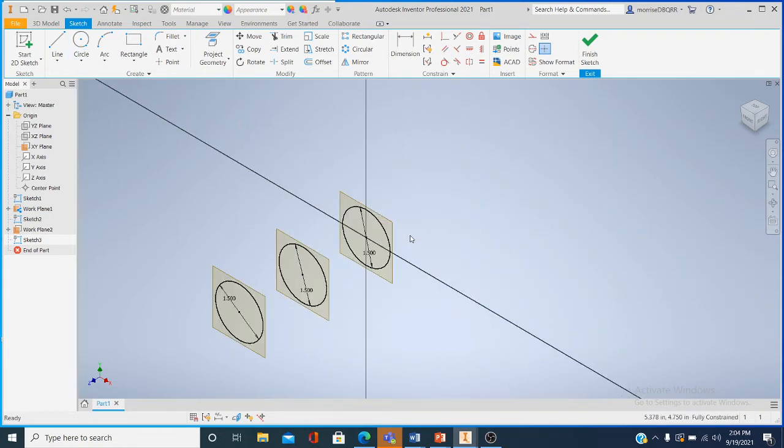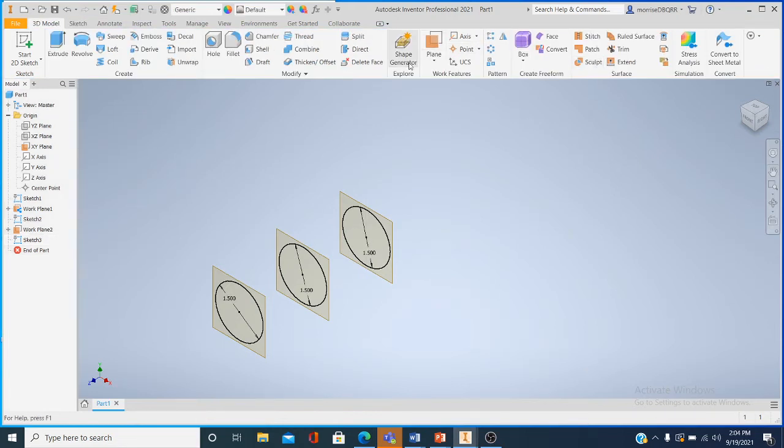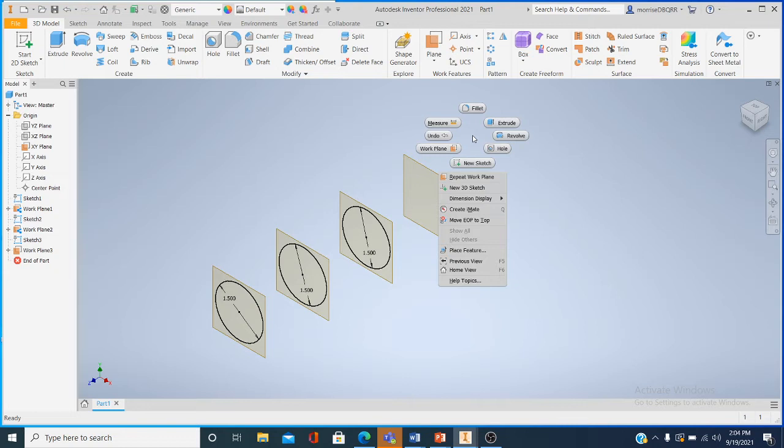All right, now we're going to make 1 more offset plane. That's going to be 2 inches, but this time we're going to create a different profile. So finish the sketch, go to plane, click on this plane, hold down your left mouse button, and we're going to drag it back at negative 2, enter, right click. I got a bad habit of doing that.